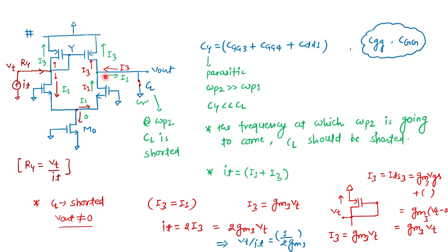Then what will happen? This I1 is equal to I3, as we can see from here. I3 equals I1 as my complete I1 is folding here and going to I3. One more thing we should see: this I3 current flowing through M3 is also copied in the M4 terminal.